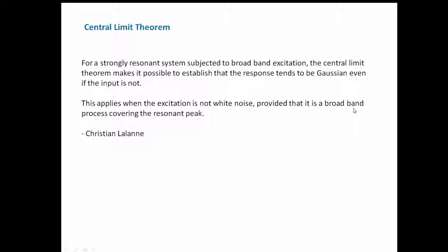And our signal with kurtosis equal to 5 was non-Gaussian. And whether or not it was white noise, we have to be a little careful about that. I think this is a wonderful statement. We might substitute non-Gaussian there for non-white. But again, perhaps when we state that a signal is white noise, we are assuming that it's Gaussian distribution with kurtosis equal to 3. So if that's the case, which it probably is, then this statement's perfectly fine as is, which is a roundabout way of saying our kurtosis equal to 5 signal is not a white noise signal.